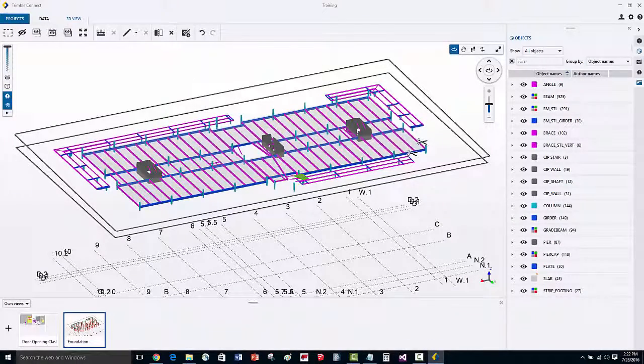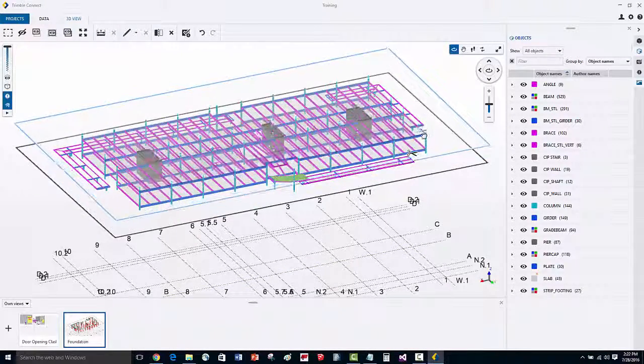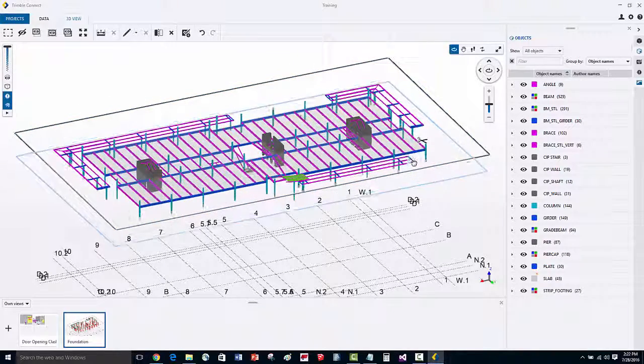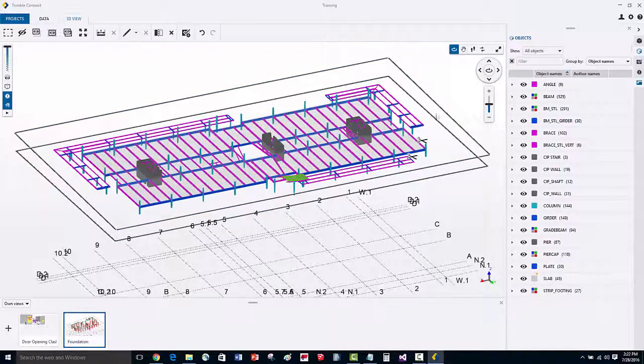So now I added another clipping plane, which is in the opposite direction of the first clipping plane I had, so that way I can easily clip above a floor as well as below a floor. And now I'm clipping this specific second floor framing steel. I'm going to repeat the process of creating another view, and we'll call this second floor.